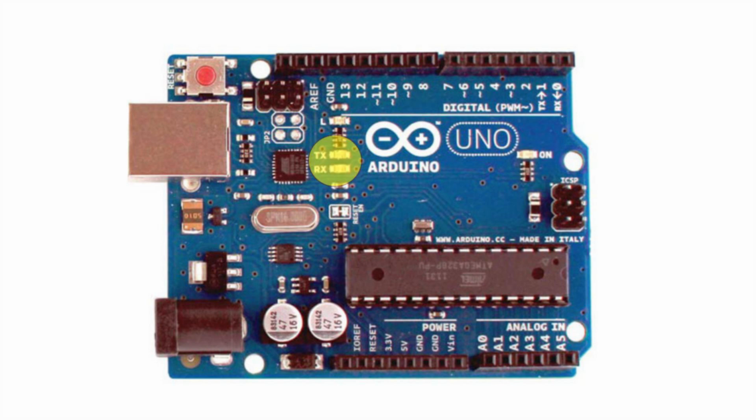First of all, let's find and identify where the LED is on the board, as there are more than one. This one on the right is the power LED, and it is on every time you power up the board. It is marked ON. Those two, marked TX and RX, show the activity of the serial communications, for instance when you upload a sketch on the board. And finally this one, marked L, is the built-in LED that we are going to control.